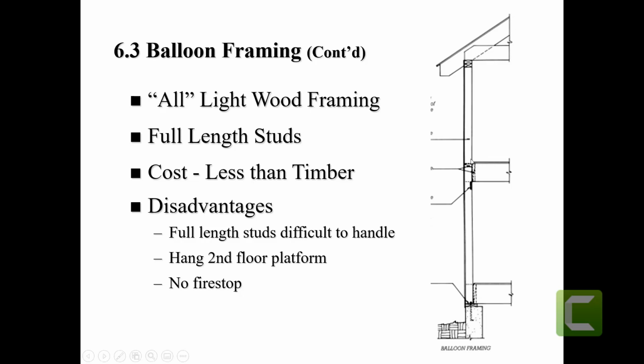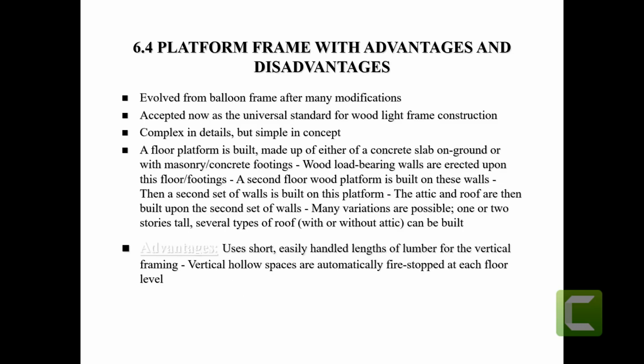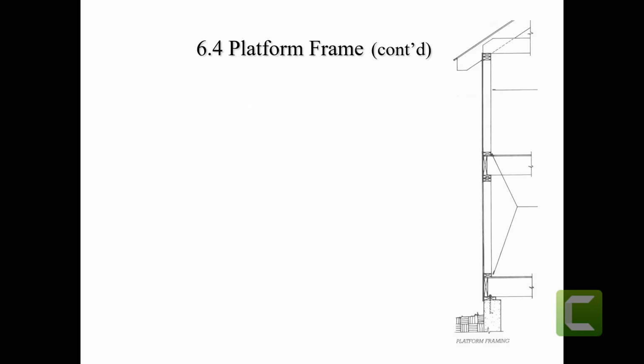Now, I want you to also take into account the disadvantages of having such a long piece of lumber. It might seem stable, but you have to understand the fire hazard of the continuous stud. If one stud starts burning, there's no way to fireproof this cavity good enough where the fire can't just simply jump across from one floor to the other. So fire spreads much faster. No matter how much blocking you add, it won't be as sufficient as cutting the stud and then going with a different stud. Second disadvantage is putting it up. It is far more labor intensive to tilt a wall of that size.